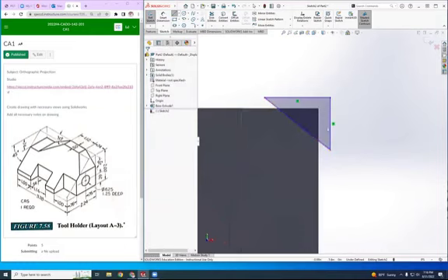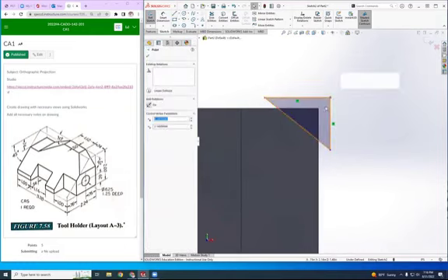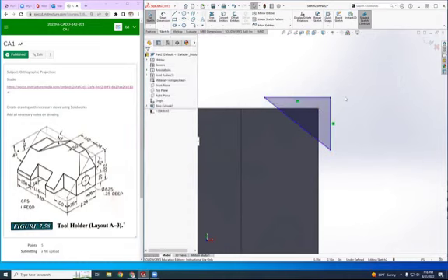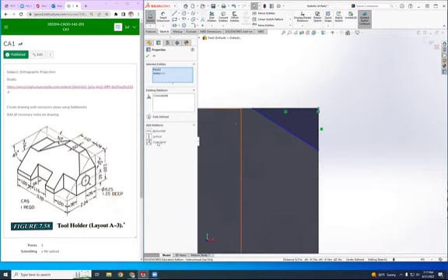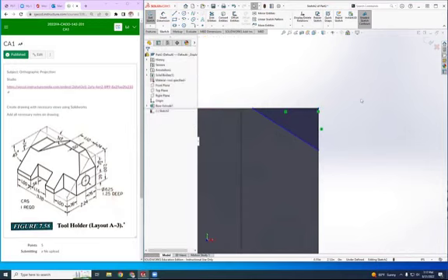It's a closed sketch, closed loop, because it's shaded. I want this point and this point coincident. So I need to hold down my control key, click on this point, click on this point, and make them coincident. So coincident is my geometric constraint. I highly recommend to do geometric constraints before dimensional constraints. Always. That's a big note on your notebook too.